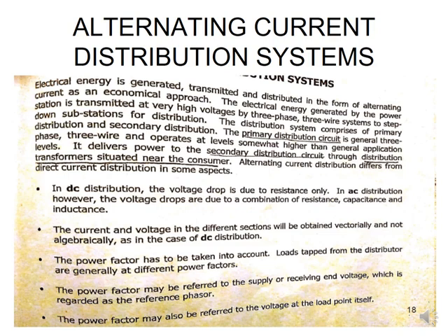So in these AC systems, we've got a primary and a secondary distribution circuit. Your primary one is usually at higher voltages, and then they get stepped down by a transformer into voltages that can be delivered to us as consumers. There are a few differences, therefore, between your AC and your DC distribution systems, and these are stated below.